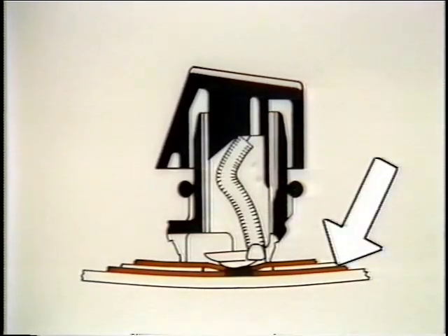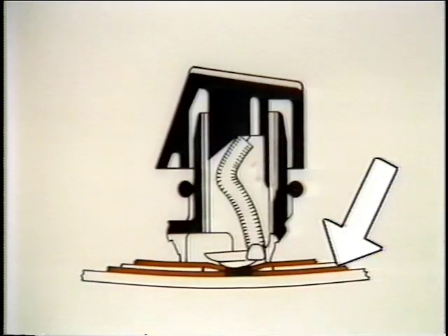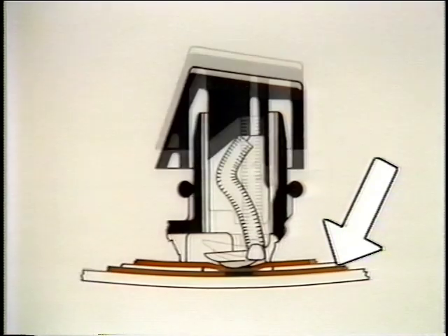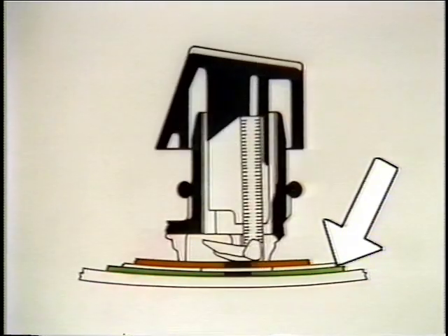When the membrane switch closes, the 5 volts DC is applied from the sense line to the drive line. When the function board scans the drive line, it notes that the switch is closed and sends the appropriate instruction to the printer board.